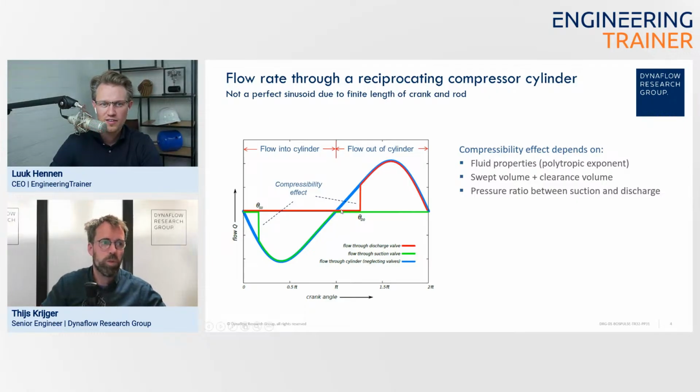So what we call the discharge of the compressor. Yeah. And then basically the same thing happens. So we start moving the piston back, compressing until the pressure within the chamber reaches the pressure at the line side, the discharge side. Yeah. At which point that check valve will open and we'll get this sharp step, and then a flow pulse.